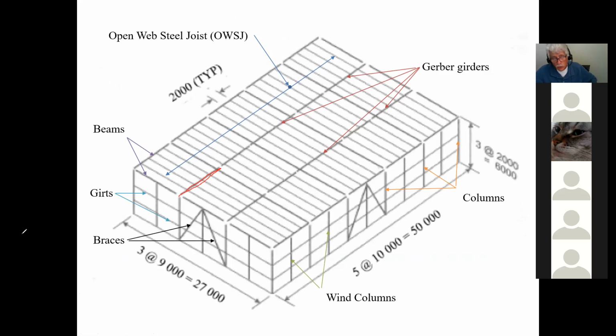The joists. So all the loads on the joist are going to come and rest here. So what kind of a force am I going to create on the girder? A normal force. A concentrated force. Normal, perpendicular to it. I like that word normal, perpendicular, but concentrated, okay?